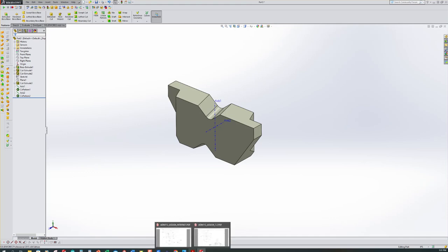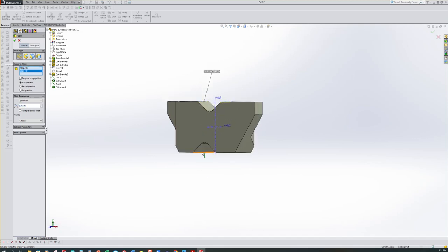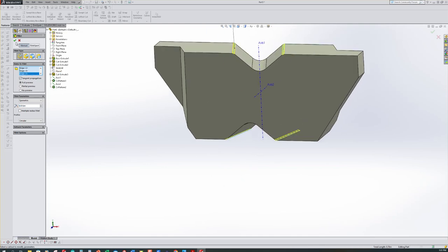Now as I'm looking at the drawing, it looks as if we have a radius up here on the top. Sometimes it doesn't like to pattern the fillets, but we want to give it a 0.015 fillet. And I want to click here. And sometimes you can come out in your flyout and see if it's going to give you the option that you're looking for. And you only have to pick certain things. It's really not going to give me the option I'm looking for. So I want to pick that one, come down here to the bottom, pick it. Nope, wrong one. Pick this one and this one. That's why it's always best to kind of roll it around and take a look at it. So we want to accept that,